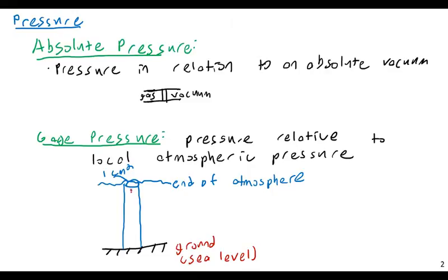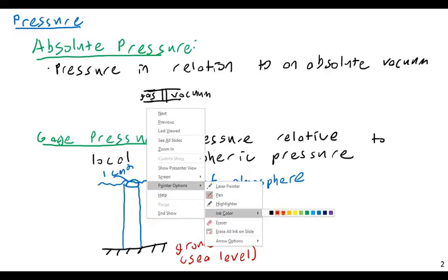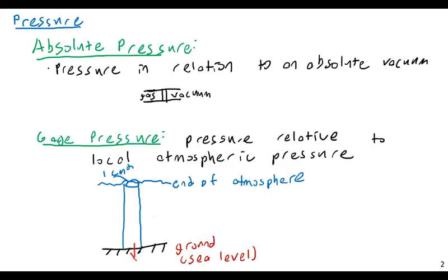And so the question is, how much mass is contained in that cylinder, or how much weight? And it turns out it's approximately 10 newtons at the bottom of the cylinder. That doesn't sound like a lot, 10 newtons, right? That's not very much at all. But when you think about that, 10 newtons is approximately the weight of 1 kilogram. And that's on 1 square centimeter of area.